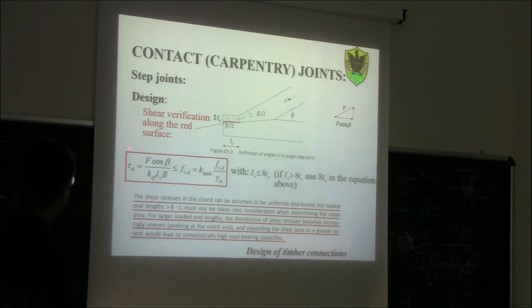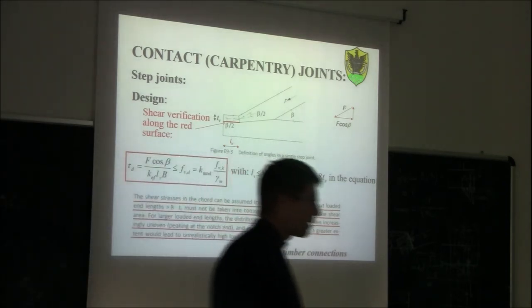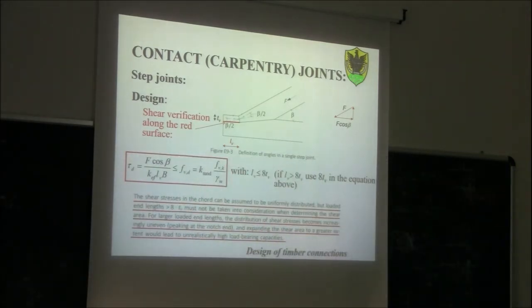So this stress will be compared, of course, with the design longitudinal shear strength, calculated as usual. Okay? So those are the verifications to do in this carpentry connection.